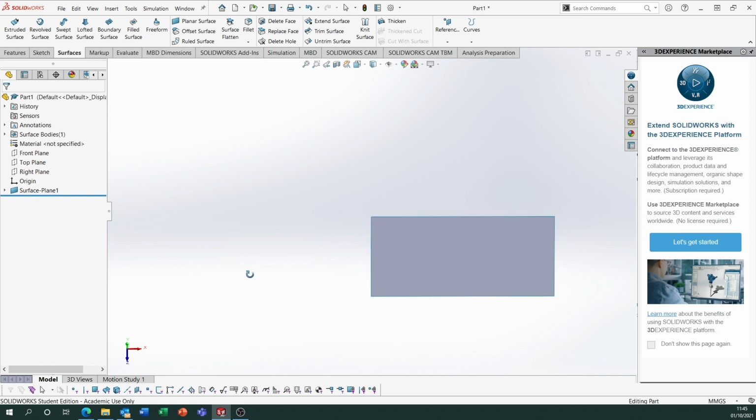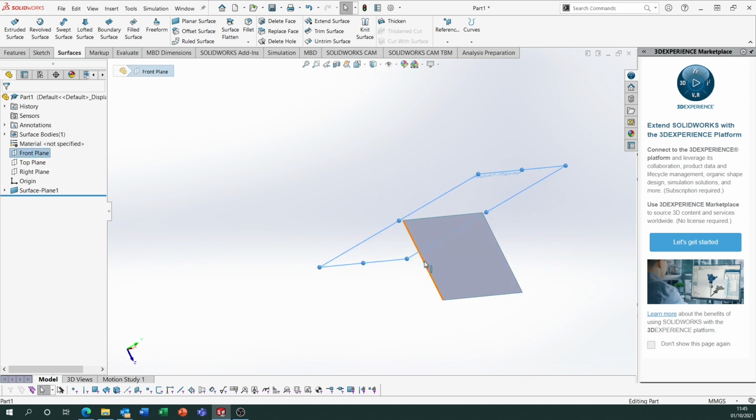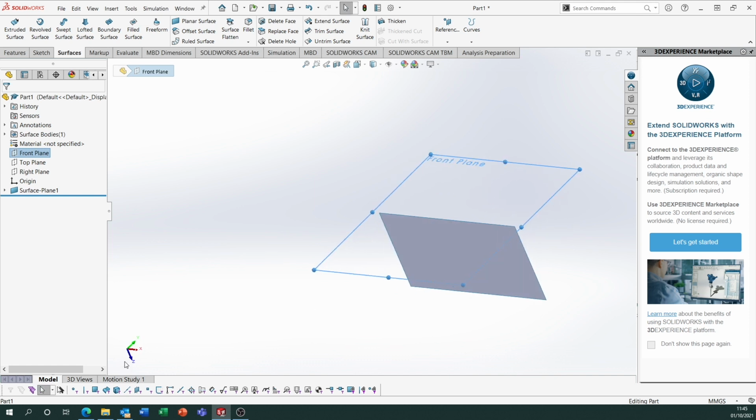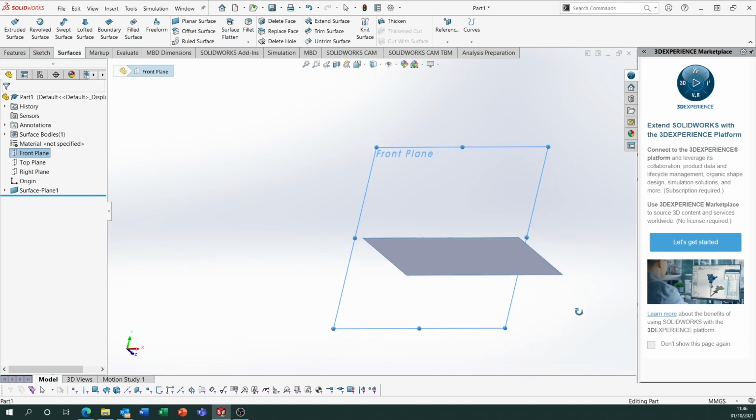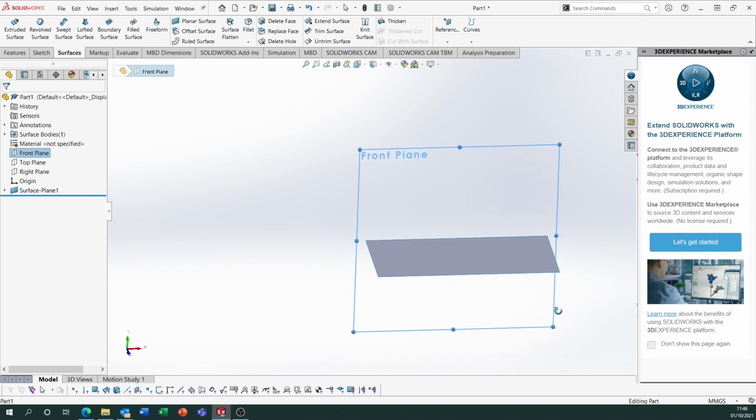Now at this point, before you do anything more, I want you to make sure that it's sitting in the right position. So if the front plane is there, that the horizontal plane is coming forward from that. So this Z arrow down in the bottom left corner where we can see the axes, the horizontal plane should be in line with that Z axis there. The vertical plane should be in line with that Y axis. If it's not, that's why it'll come out back to front or upside down on your drawings. So if it's not, fix that now.